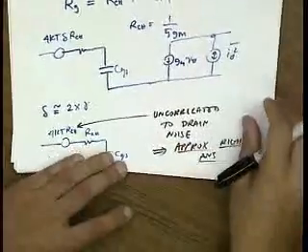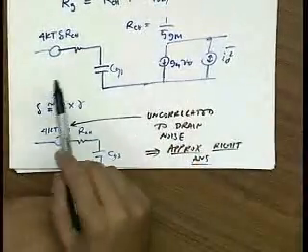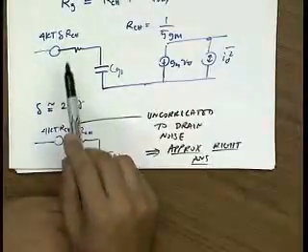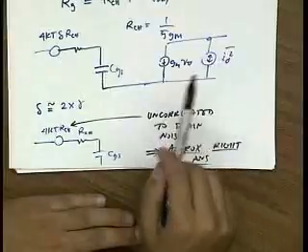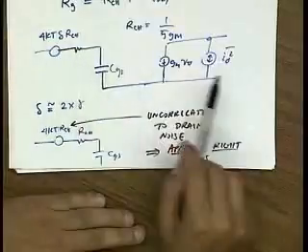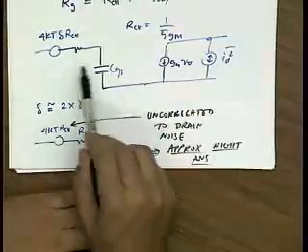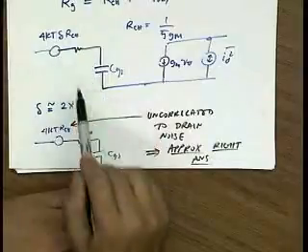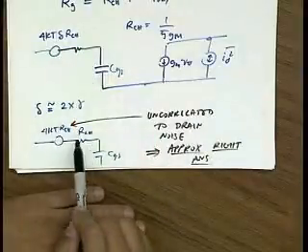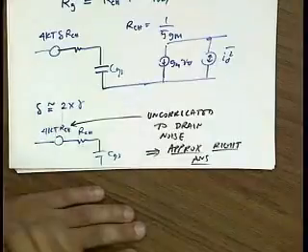Yes? Sorry, can you briefly explain why that? Why? Well, what happens is that the part that's correlated kind of cancels out some of the noise. When you actually go through the noise analysis, you find out that because this is correlated to this noise, when you calculate the minimum achievable noise figure, you can cancel out some of the drain noise with the gate noise. And that's why the effective value of the independent noise is smaller by this delta factor. Okay? It's very complicated, actually.